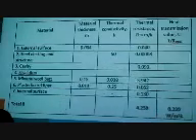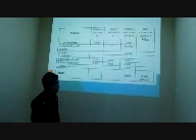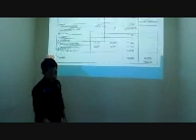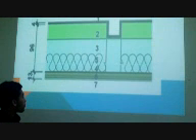And this is the RTTV, the last part. You can see the materials that we use to build our roof. We use steel decking and structure, mineral wool bed, plasterboard liner, and the internal and external surfaces. The total R that we get from these materials is 4.259, and the U value is 0.235. And this is the cross section of our roof.